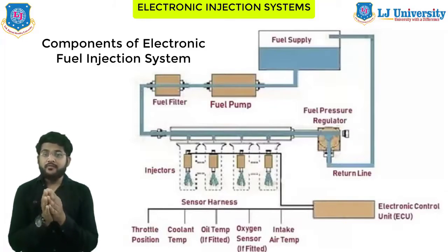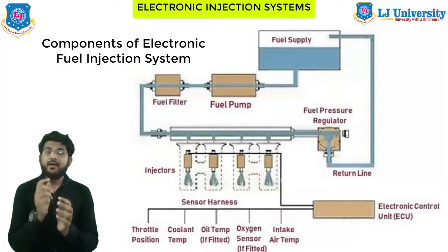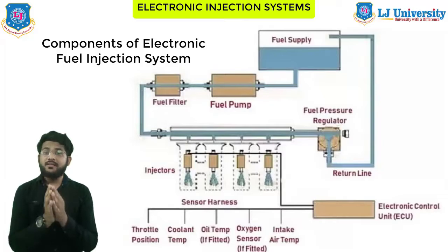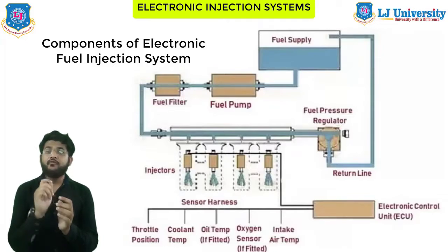The throttle valve actuator considers the 0 degree position as a pulse of 1 millisecond and 90 degrees as a pulse of 2 milliseconds within a period of 25 milliseconds. Considering this timing constraint, the reading of the sensors and the calculation of the acting time for the actuators should be processed in at most 15 milliseconds.